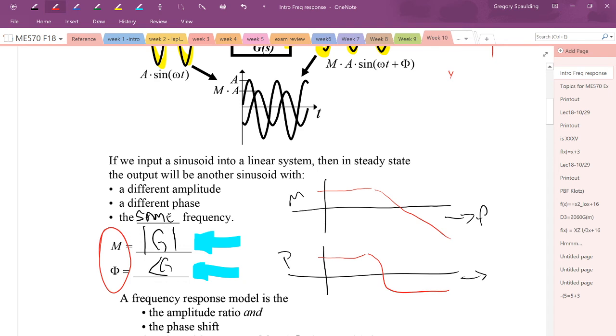We've got to calculate it at a low frequency and a little bit higher frequency and a little bit higher frequency, higher. And this would be the brute force method of calculating it, just calculating a bunch of points along here of the magnitude ratio for a variety of frequencies, and then plotting a line through that. It's likewise for the phase. Point for frequency, and we would end up then plotting a line through that, and we could create our magnitude phase plots for that. And so we want to see the mathematics for that, and we're going to explore that. And then once we get the mathematics down, we're going to see if we can then learn how to sketch it and kind of shortcut this a little bit. And so that's where we're headed in the next lecture.